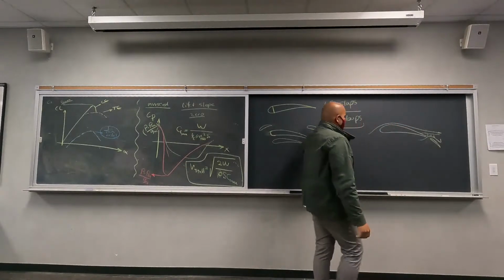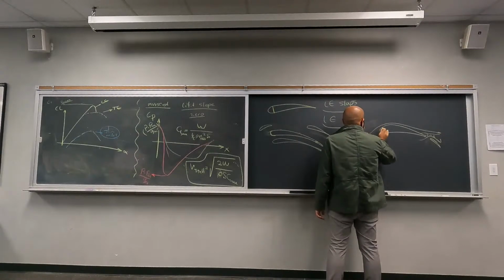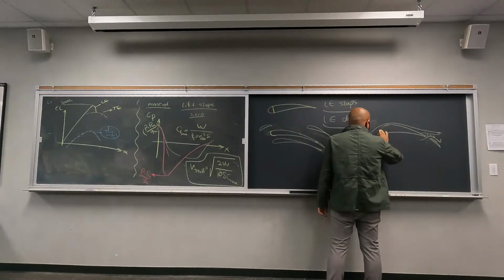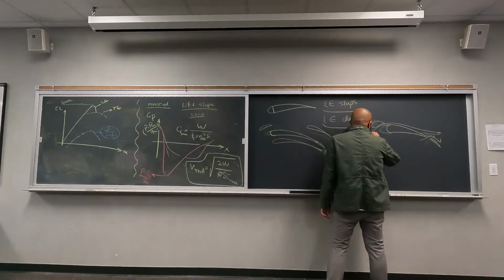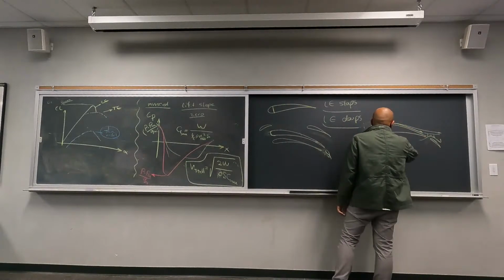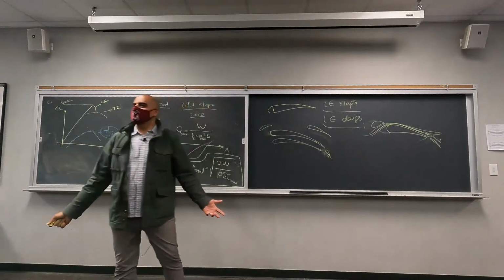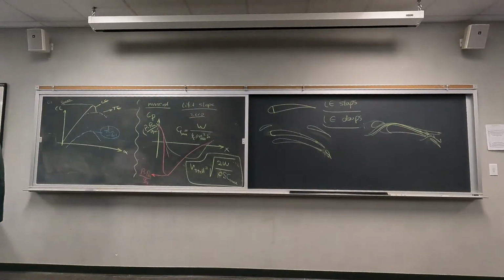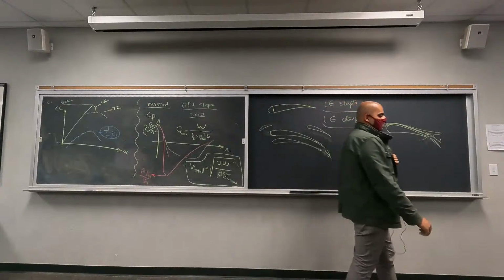But we can actually, by introducing something in front, so let's say this is your wing, and then you release whatever that is in front to move forward, you are going to push some streamlines to stick to the airfoil. That's how you affect the flow pattern, right? You are going to minimize the effects of viscosity by reducing the boundary layer thickness and effectively reducing the flow separation, or delaying the flow separation.